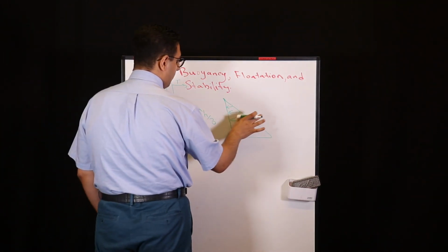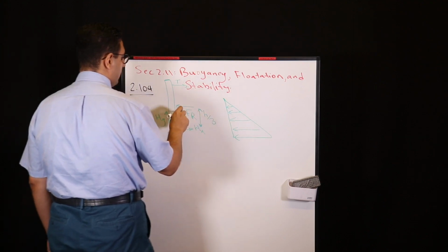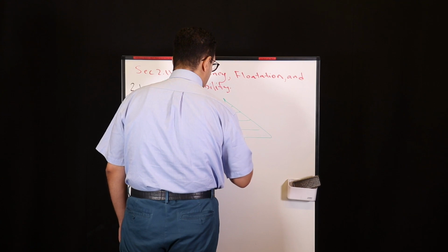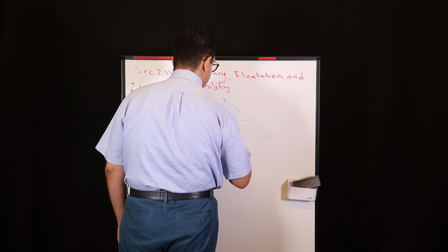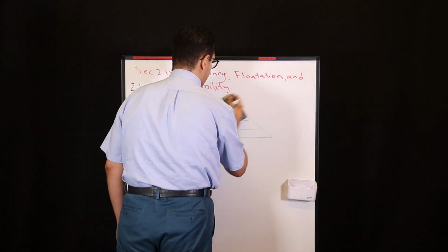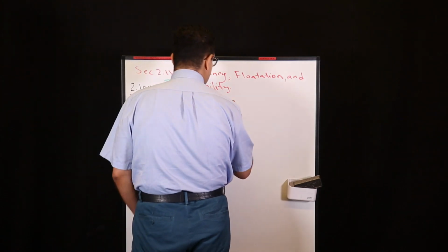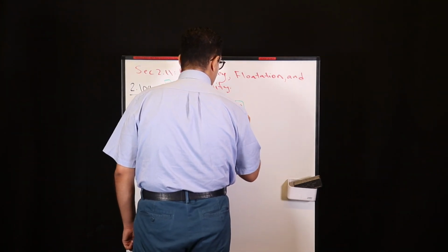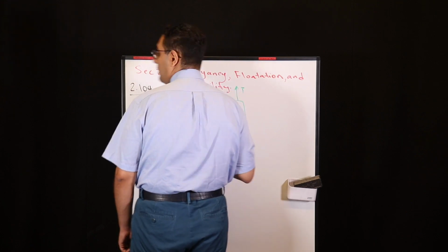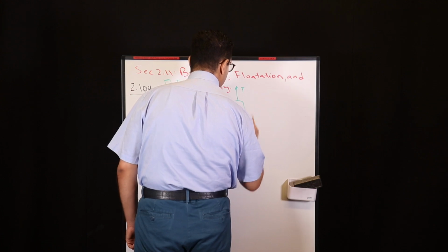For the triangle, when we want to pinpoint the location of exerting Fr, it's going to be exerted at H/3 from the bottom. And for the cylinder, we have this mg, cable tension to the up, and the flotation and buoyancy force.